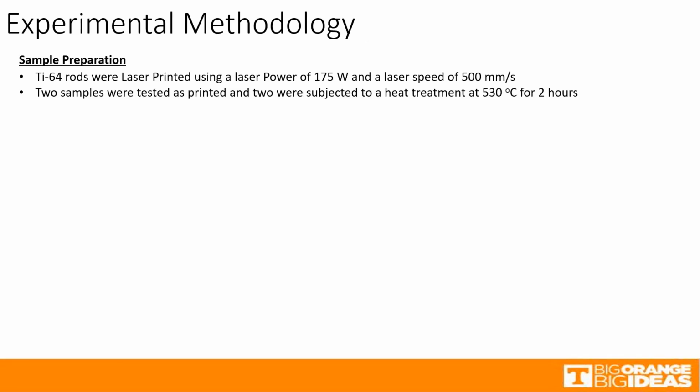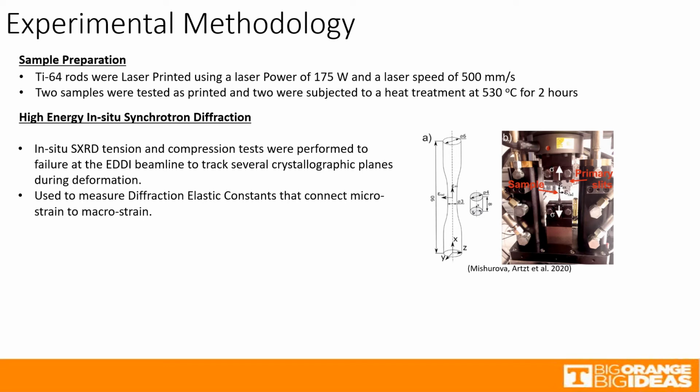Our samples are Ti-64 rods that were printed using the laser powder bed fusion process. 2 of the samples were tested as printed, and 2 were subjected to a heat treatment at 530 degrees Celsius for 2 hours. High-energy in-situ synchrotron diffraction was conducted during tensile deformation to track the evolution of several crystallographic planes. The image on the right shows our specimen design as well as orientation during diffraction measurements.